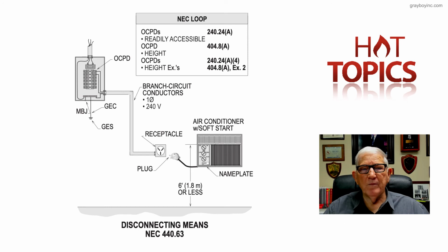And then to cap it off, read 314.1, which deals with items that could be used as an outlet. You notice a conductor is not mentioned there at all, but it goes through a complete installation up to the time you pull the conductors and terminate those conductors at that receptacle or disconnect or at, say, an AC unit. Now notice this is cord and plug connected and gives you the rules, and notice that the attachment cap can be used as a disconnecting means in relationship to the receptacle.